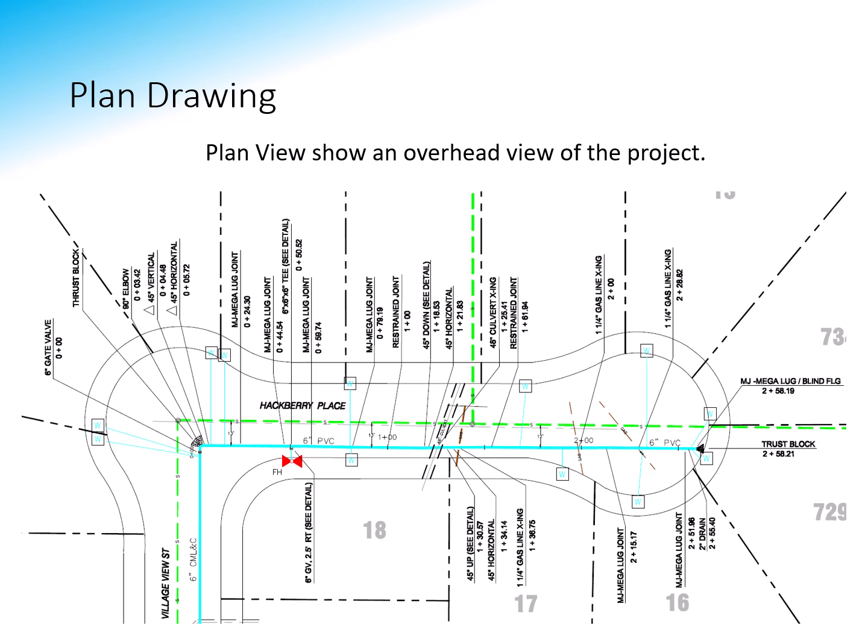There's other identifying information, like an end cap here. We've got a storm drain crossing here. Here's a fire hydrant. This green line represents sewer, and you can see they've got a sewer trunk that flows through here. Even on the main itself, it should be calling out what size main that is. That print's a little small for me, so I can't tell you exactly what it is right now.